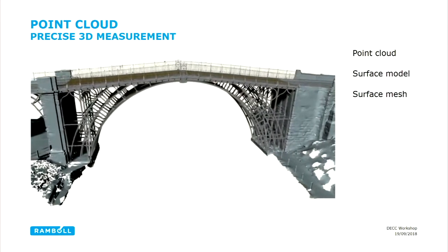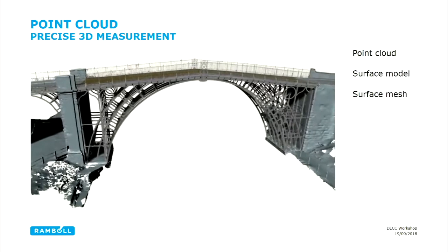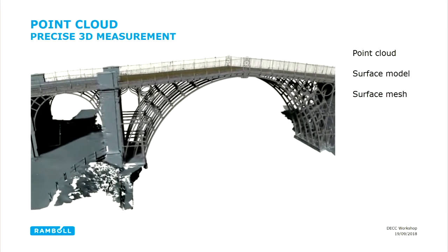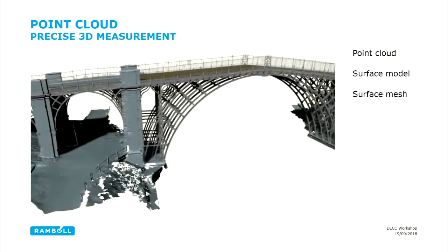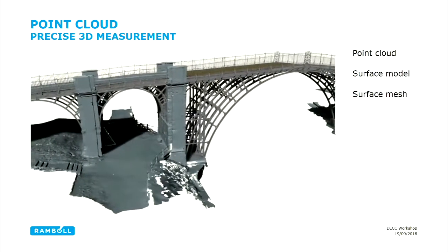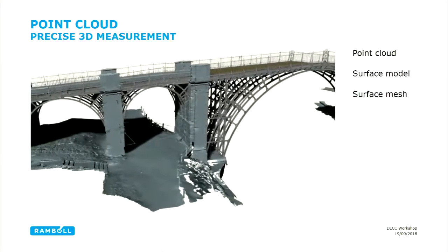And then you think, well, hang on a moment, on a hot day that bridge is bigger. So there's issues. It's quite complicated to achieve really good accuracy. And the next stage is to create a surface model. The main span we did fairly rigorously, so we've got surfaces that are all kind of joined up and mathematically defined.